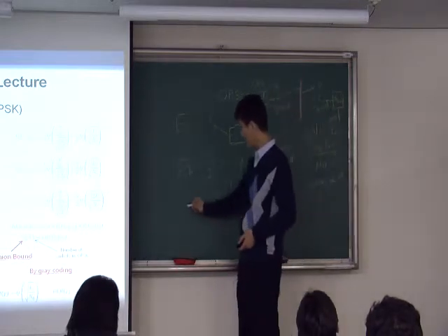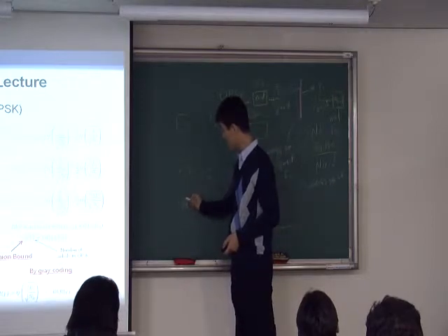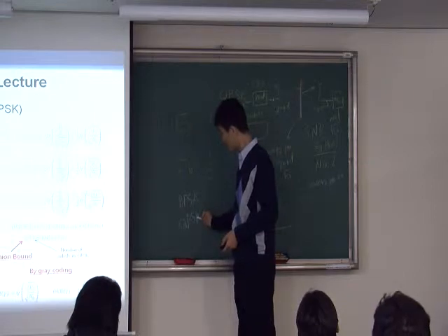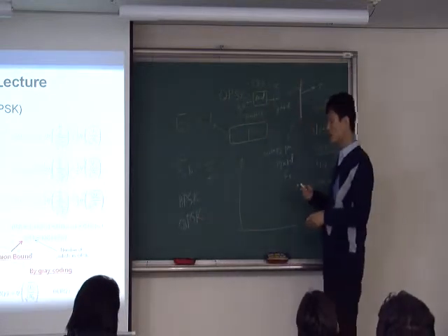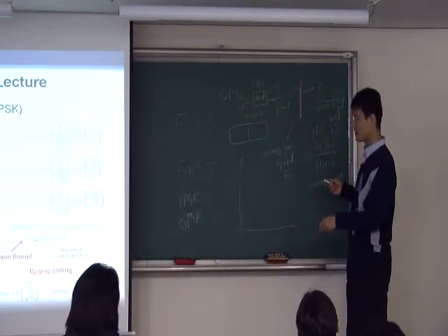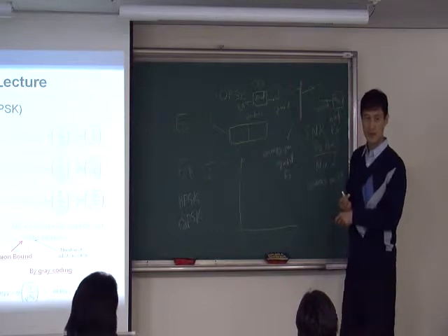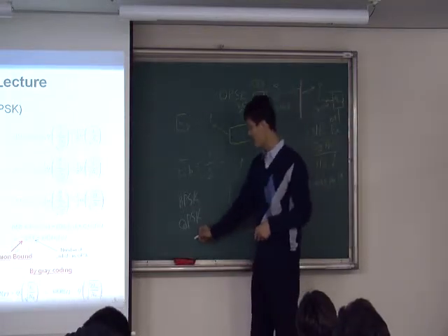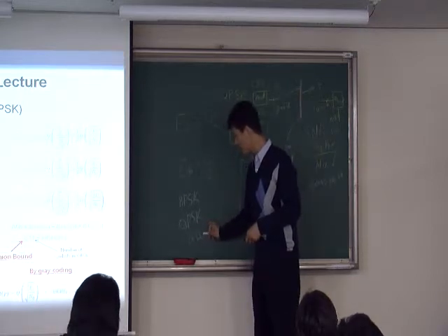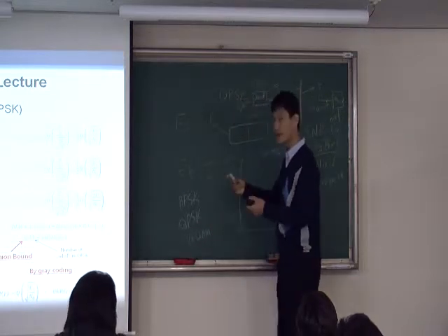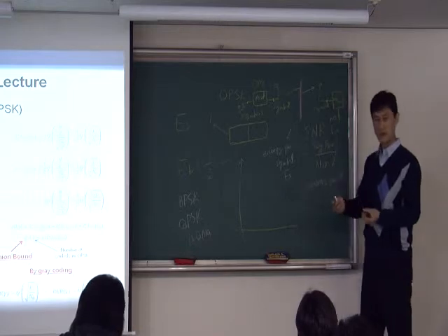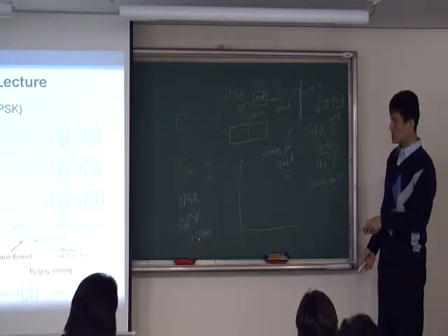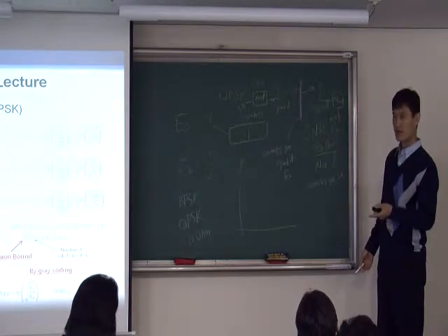Now I'd like to compare BPSK and QPSK. You know that when you typically use a higher modulation, you get a higher error rate. Okay, typically that's the case. If you use, let's say, 16-QAM, you can even have a higher bit error rate. Higher bit error rate basically means bad, right? Higher modulation typically means higher error.